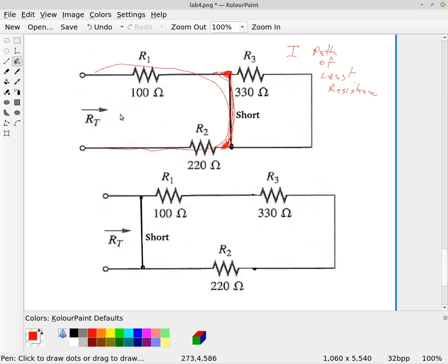So the total resistance then of this circuit would be 320, and again, if we're putting it in Blackboard, don't forget your decimal point, ohms. So 320 ohms. All right, because it will bypass this resistor of 330 ohms, because it's much easier for it to just take the shortcut. And because whatever this wire is here, this wire has fractional resistance compared to 330 ohms of resistance.